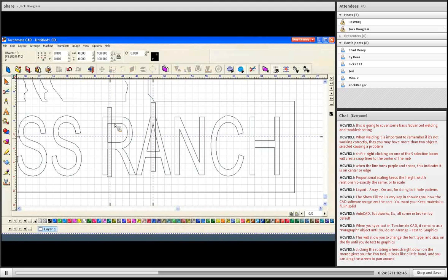You know, if that's critical to the part, the same thing with this R on the side now, if I hold down Shift and right click, it gives me a guideline, particularly on the edge of that R. And there's another guideline right there as well. So there we go. And again, if it's something artistic or it's not critical, it doesn't have to be done. But if you do need centered or aligned to a certain line, breaking the path and then having these as individual objects. But one thing to remember now is they all need to get selected when we weld this all together.